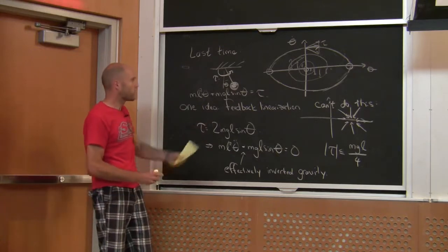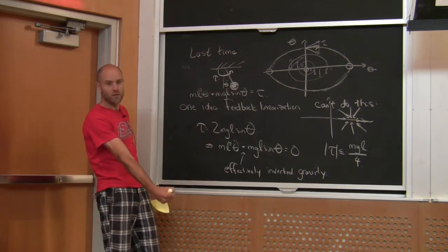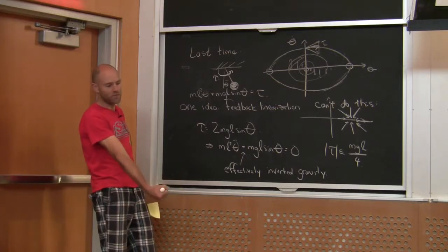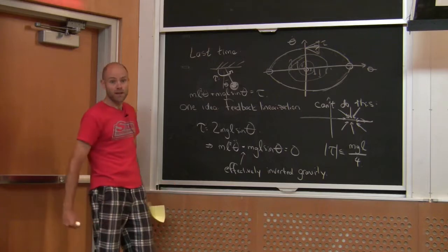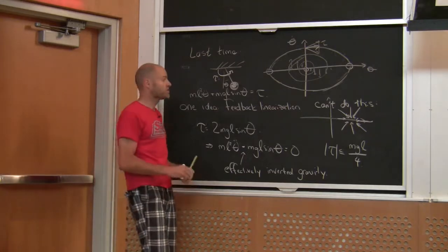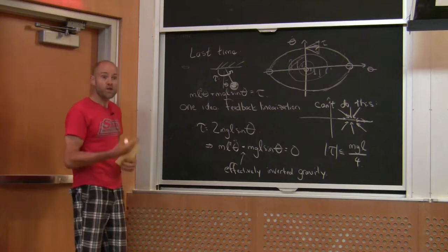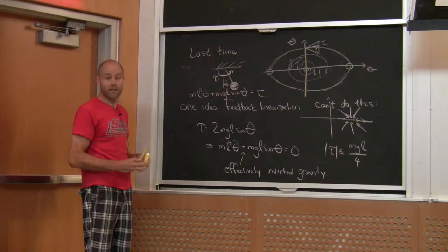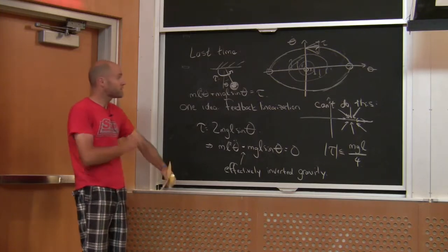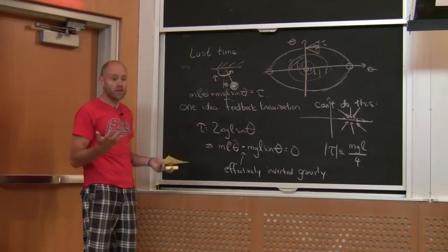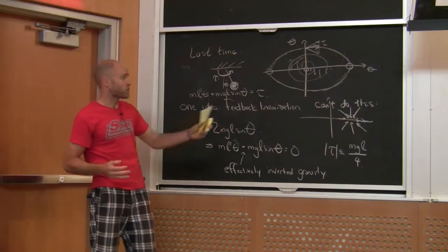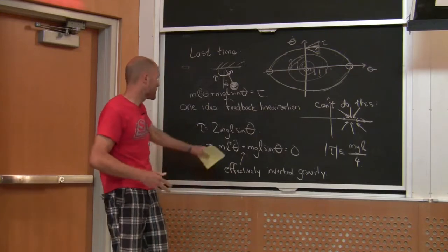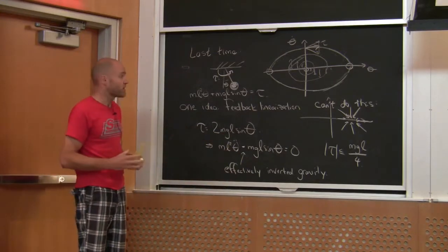And you can do that, and what you'll see is that it'll get stuck at these sort of local minima, where it'll be fighting against it, it'll go to the equilibrium that we found from the constant torque input of the pendulum, and it's not going to achieve your goals. And if you think through for the pendulum what you have to do, the reasoning actually gets pretty complicated, right? If I have only a little bit of torque to give, then I can tell you the answer, and we'll see the answer in a sort of nonlinear control particular to the pendulum kind of way, that we can write down a set of equations that will do a nice job of this.